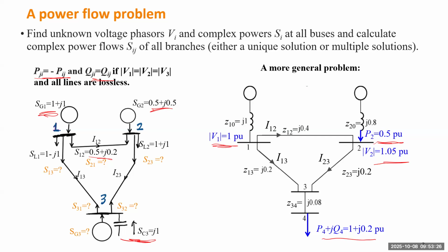So the objective of power flow is to solve for each bus in this figure, no matter which type it falls into. For bus 2 we need to know the Q and the angle, for bus 4 we need to know the voltage and angle, and for bus 1 we need to know the angle, P and Q. Actually, there's also bus 3. Bus 3 doesn't connect directly to any load, but we know this is also a load bus because the P and Q are both 0. It's simply 0. So we still need to solve for the voltage and angle at that bus. Okay.